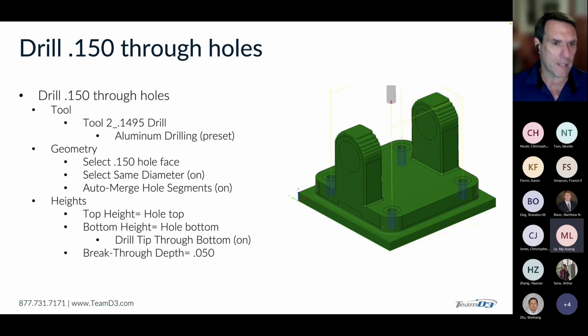But in a little while here, we'll be doing a drilling operation with a milling tool. It'll be an angled milling tool that we'll use to create a chamfer. So the short answer would be yes, you can go back and forth. As long as you've got the tool, you can misuse it in whatever way you want, or you can use it however you like.